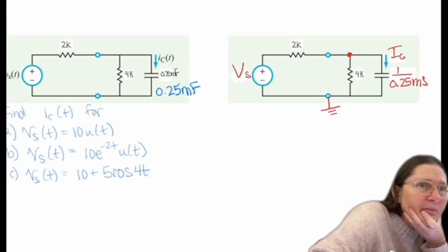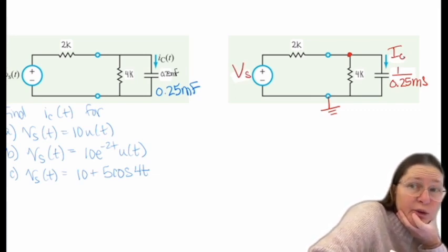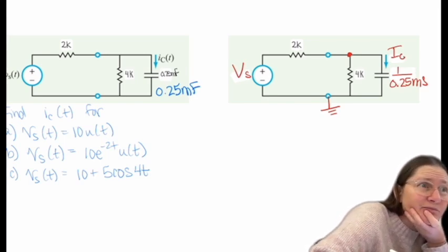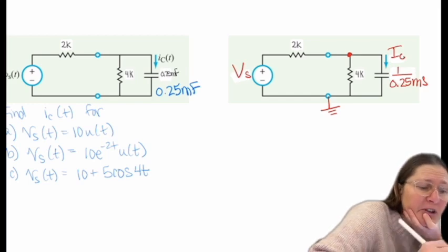Do we have to do that with Fourier as well? Yep, with Fourier you just don't have to worry about the initial condition. It's just the 1 over resistive part, or 1 over CS, 1 over ZS or LS. Okay, that makes it a little easier.